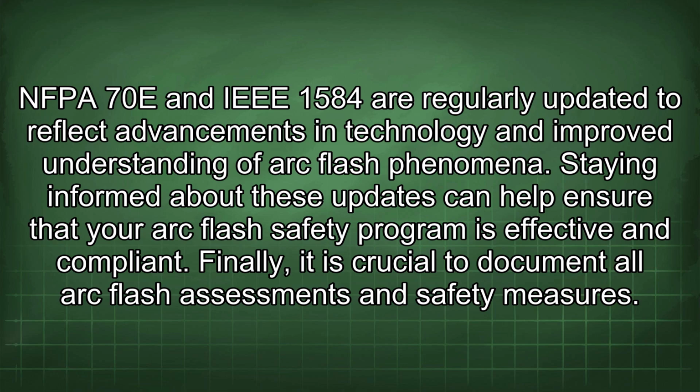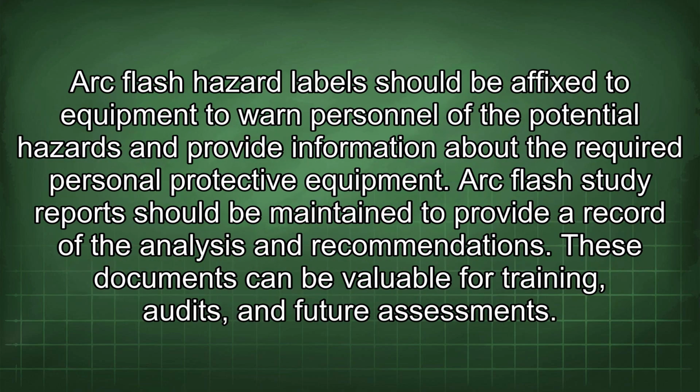Finally, it is crucial to document all arc flash assessments and safety measures. Arc flash hazard labels should be affixed to equipment to warn personnel of the potential hazards and provide information about the required personal protective equipment. Arc flash study reports should be maintained to provide a record of the analysis and recommendations. These documents can be valuable for training, audits, and future assessments.